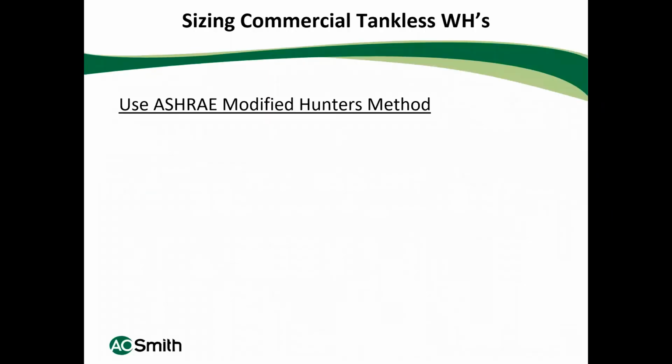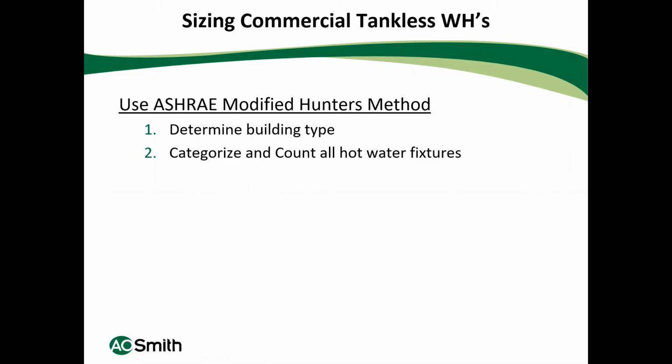So moving off of emergency showers, and going to talk about tankless here. We use what they call the ASHRAE modified Hunter's method for sizing tankless water heaters. So we have to determine the building type, obviously apartments, schools, restaurants. With tankless, you have to count up all of the hot water fixtures.